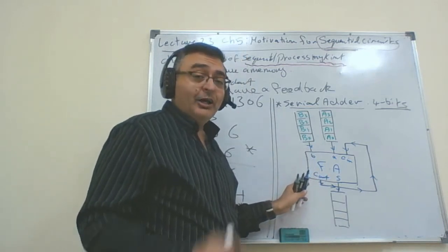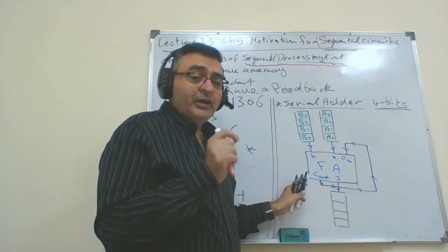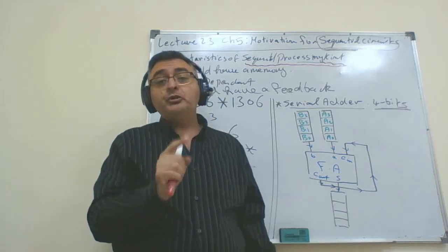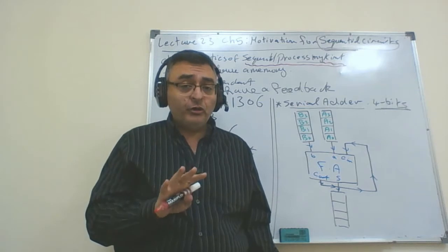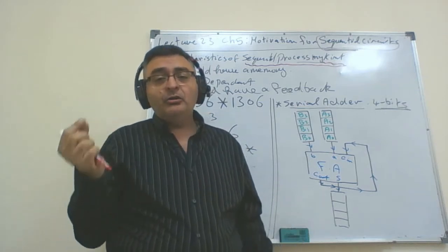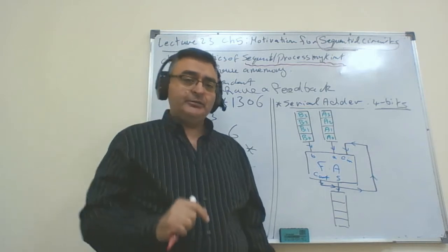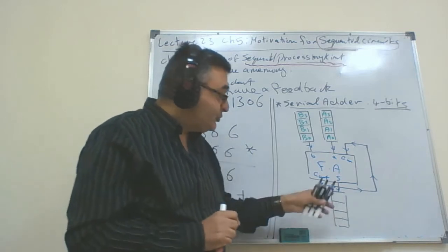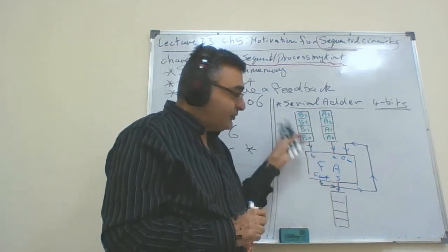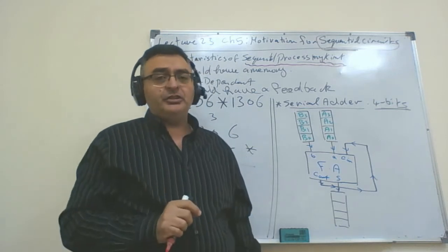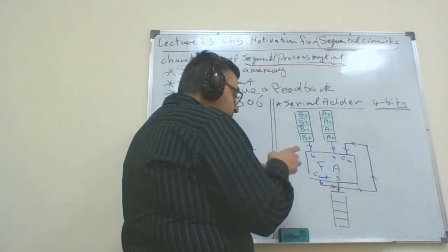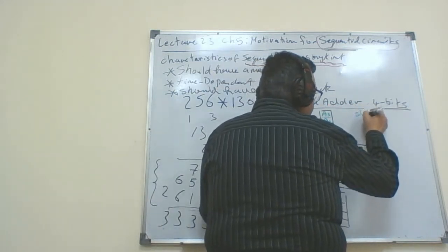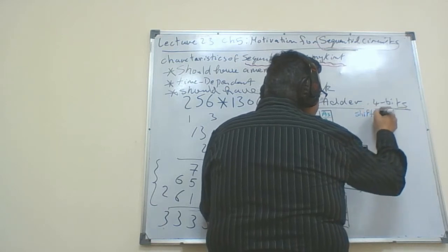First of all, I used a significantly smaller circuit. Instead of using 4 full adders to perform the 4-bit addition, I only used 1 full adder. But the full adder alone is not enough here. I have to use also those 3 small arrays that we have seen. Those are called shift registers.